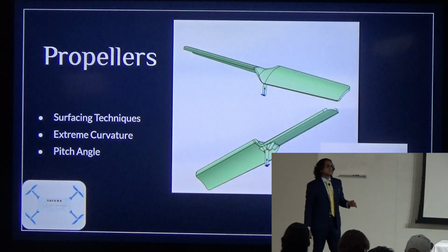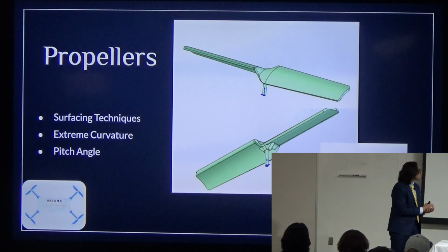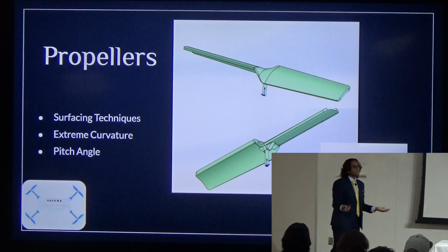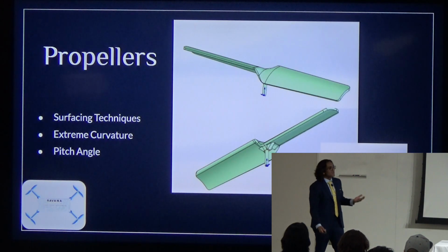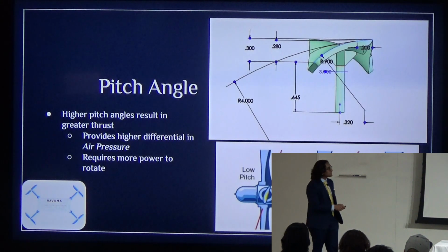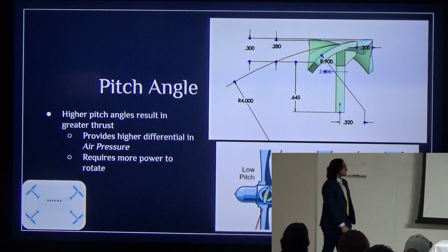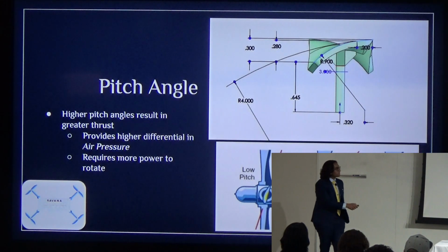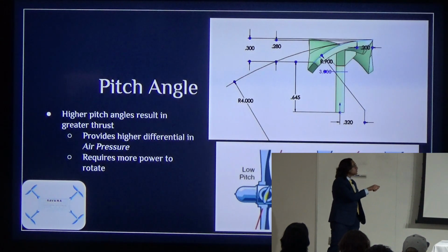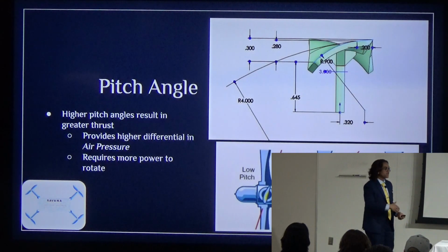And onto the propellers, this was probably the core of my research and a lot of time where I spent because of just how the airfoil is shaped, right? In SolidWorks, I do have my certification in surfacing, but it really, really tested my limits because of how many dimensions I had to put and how many dimensions I had to guess on for this, right? But in the end, my propellers were able to create a good enough cut angle such that it cuts enough air to generate enough thrust.